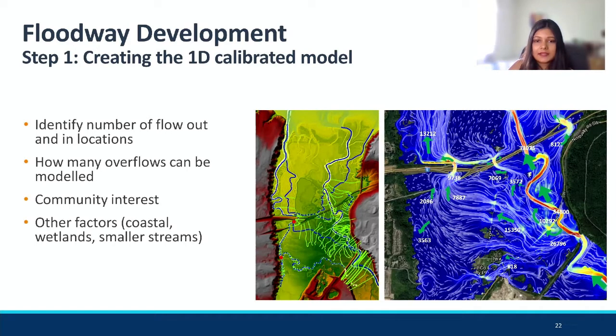And finally, since downstream of the main highway, I-5, where I'm showing downstream of it is heavily impacted by tides, and this is not a major concern area for the communities. They're never going to encroach in these areas. There is a wildlife refuge in the center, so we decided not to chase those downstream flow paths. After that, then we looked at some of the other splits. You can see there is another split where the 800 CFS is going from the south, and it's a very insignificant flow that we don't have to chase it.